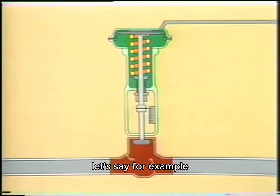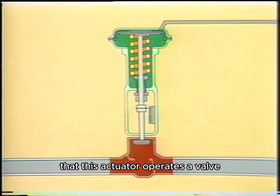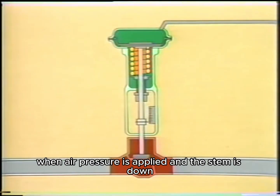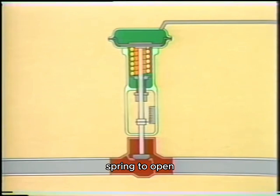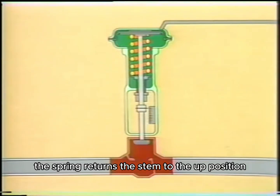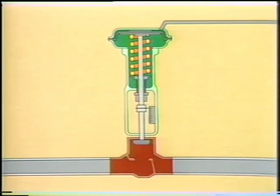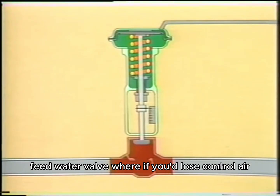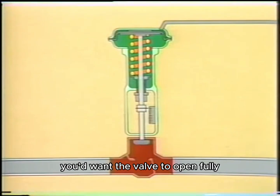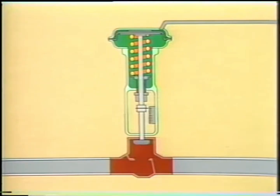Let's say, for example, that this actuator operates a valve and the valve is closed when air pressure is applied and the stem is down. This design is called air to close, spring to open. If control air is lost, the spring returns the stem to the up position. You'd find this type of setup on a boiler feed water valve, where if you'd lose control air, you'd want the valve to open fully.